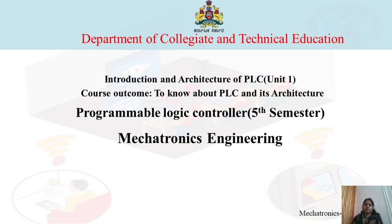After that, we have seen the working of the PLC, how your PLC works. It works in 3 steps. First, it will read or sense your input. After sensing, it will execute the logic. Then it will write or update the output. These are the 3 steps. Doing these 3 steps is called the scan cycle. It is also called scan time, and scan time is measured in milliseconds.